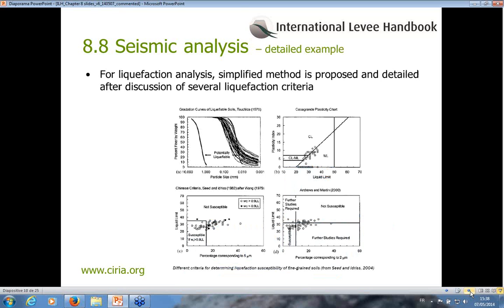Concerning earthquake-induced liquefaction, the physical processes are described in detail. Definitions of flow liquefaction and cyclic mobility are given, and the distinction is made between susceptibility to liquefaction and liquefaction potential. The governing parameters are reviewed: particle size of the soil, saturation condition, density, age, loading mode, soil microstructure, etc. And the liquefaction susceptibility criteria for sands and fine-grained soil are explained.